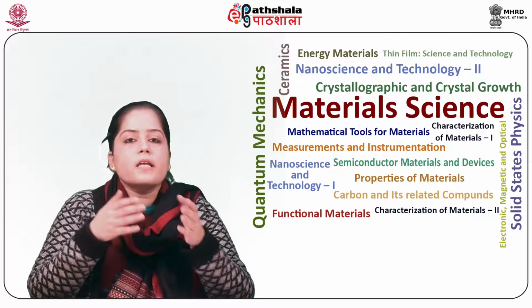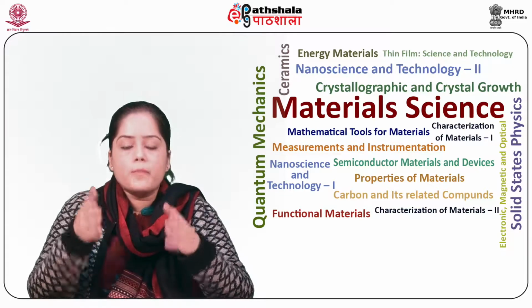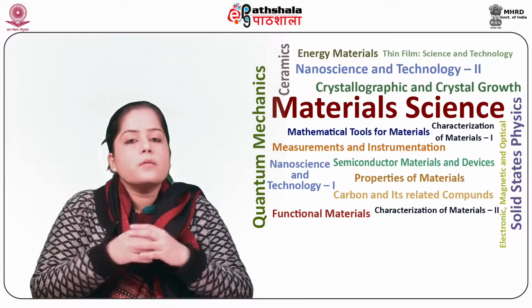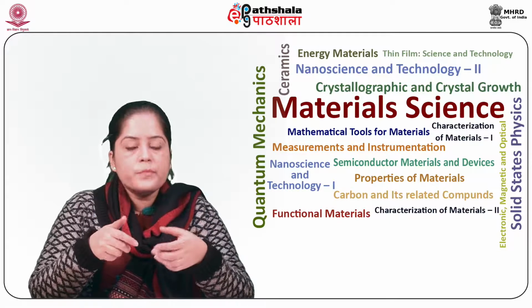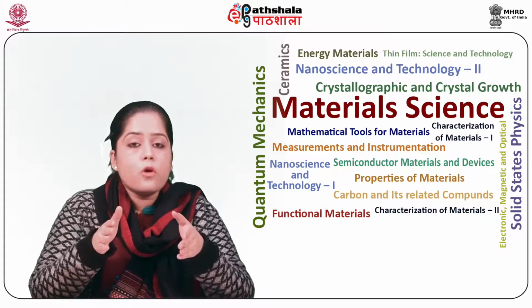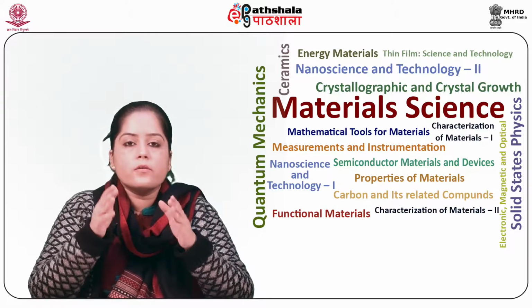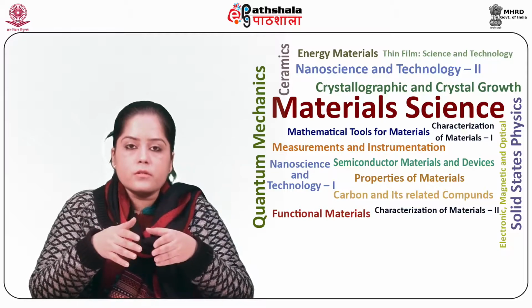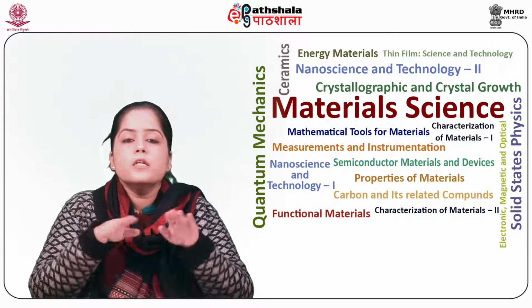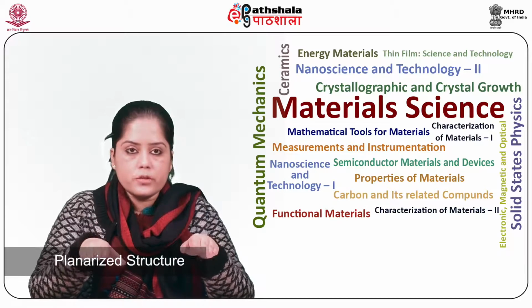Gate oxide and gate and source drain formations. The next step in the process is to form the gate oxide for the transistors. As mentioned, this is most commonly in the form of silicon dioxide. In the case of STI-defined source drain regions, the gate oxide is grown on top of the planarized structure.